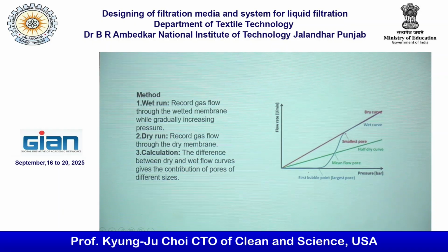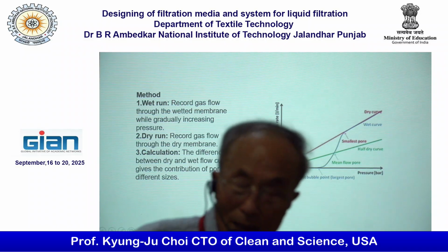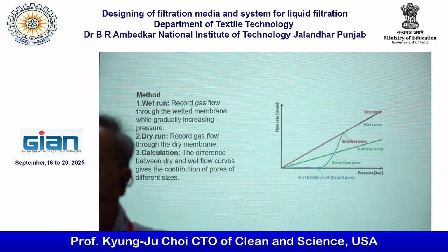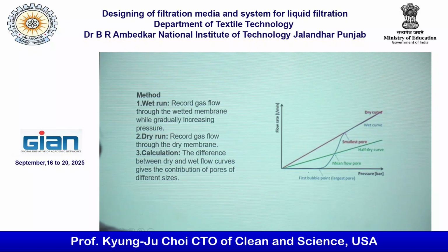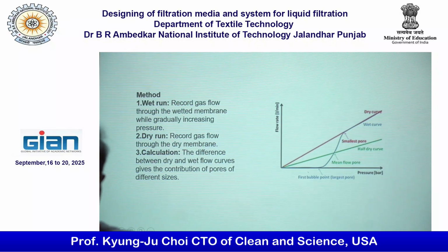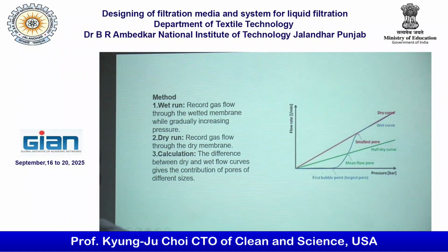The pore size distribution as well as the maximum pores. What should be the property of the wetting solution? Give some example of that. Contact angle lowest possible. So normally fluorochemical material is a good one. Yeah, that's a really good one.